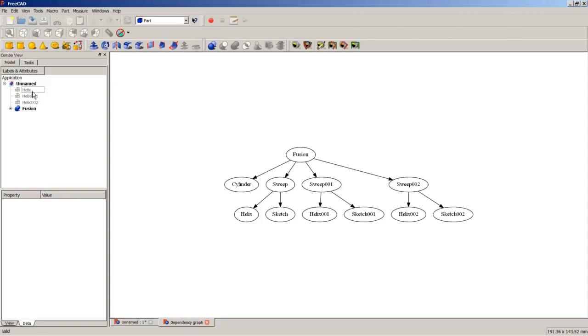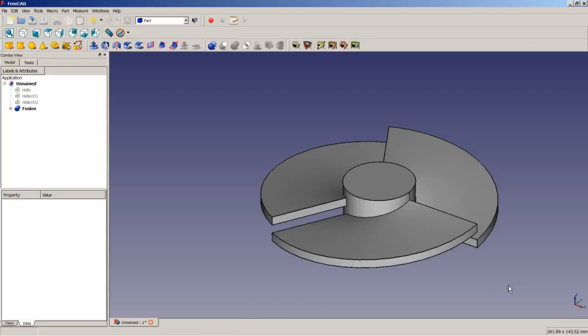Part Design has a sequential workflow order, so it is not clearly visible at first glance. If you are unsure whether you have several solids or one solid, because you have maybe downloaded a model from the internet or from a forum, you can run the dependency graph, which will tell you how many solids and which solids belong to which operation and which sketch and so on, to get this information out of the solid within FreeCAD.